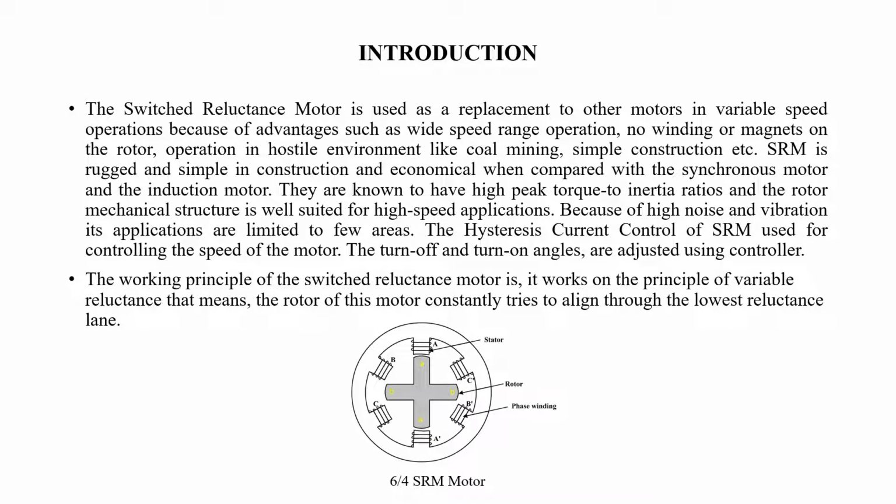First, the introduction. The SRM motor is used as a replacement of other motors in variable speed operation because of its advantages, such as simple construction, wide speed range operation, and there is no winding or magnets on the rotor. And it can also be used in hostile environments.